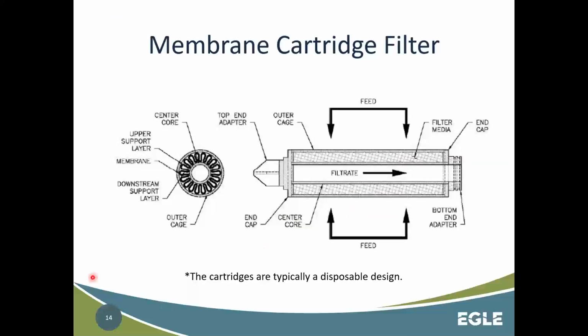And then the last type of membrane I'll bring up just to complete the classification, I guess, is the cartridge filter. This is not really something we're going to use on a community or municipal scale, but this is something you might have in your refrigerator. But you can see the water comes in, and just to increase the surface area, they kind of pleat.